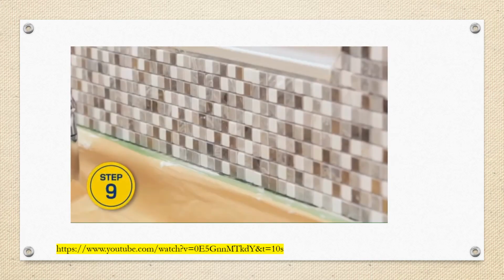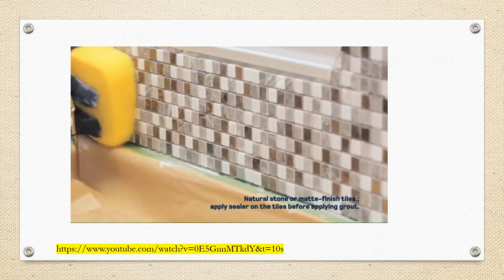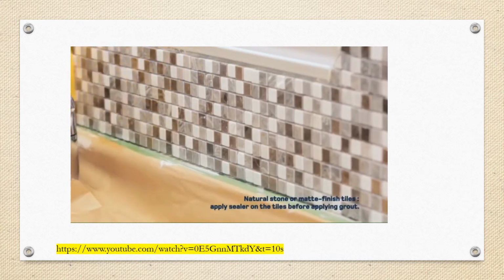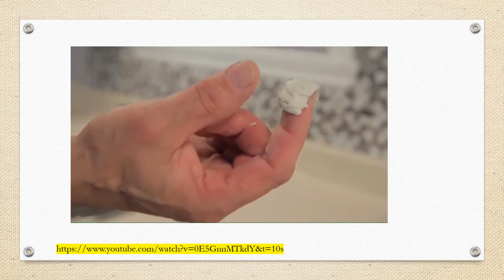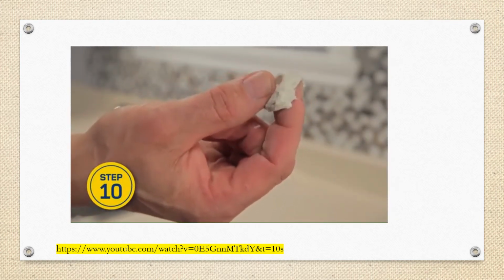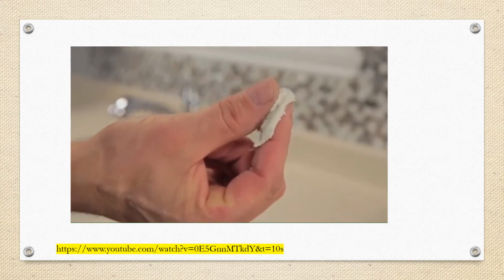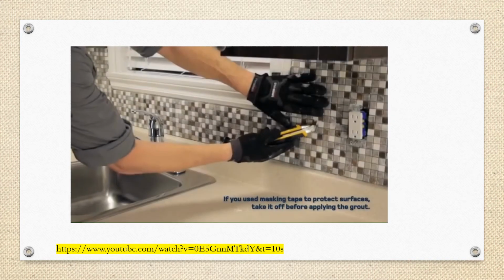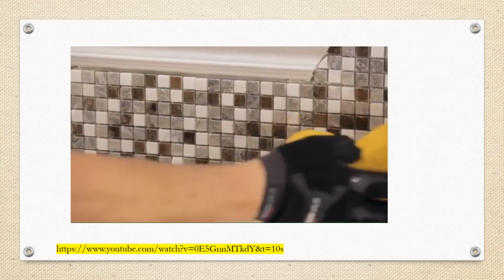When all the tiles are installed, wipe off excess adhesive with a damp sponge. Wait 24 to 48 hours before grouting. Mix the grout according to the manufacturer's instructions. The grout's color should be even and have the consistency of toothpaste. Remove the tile spacers and dampen the mosaic with clean water.